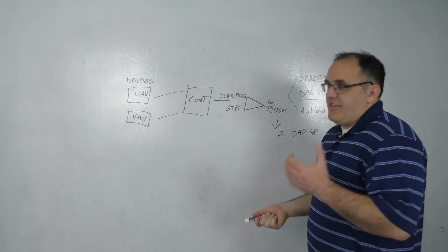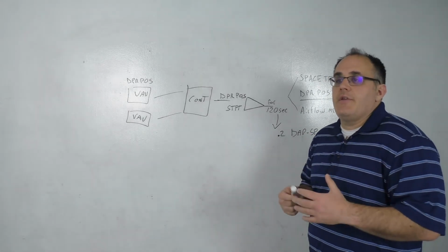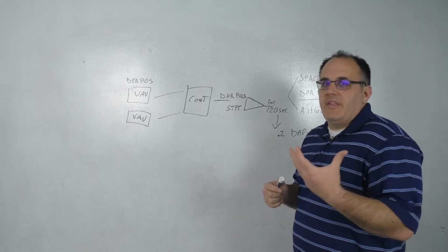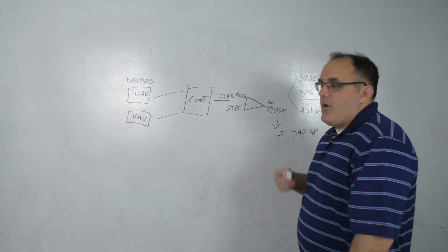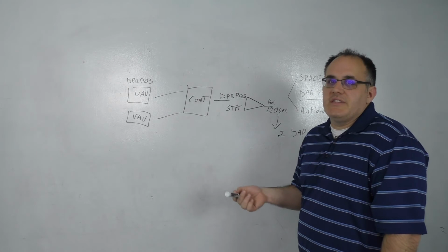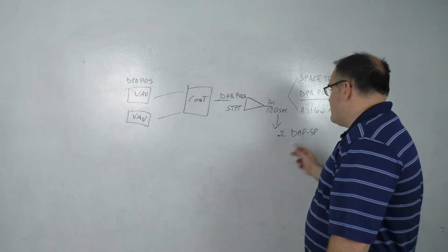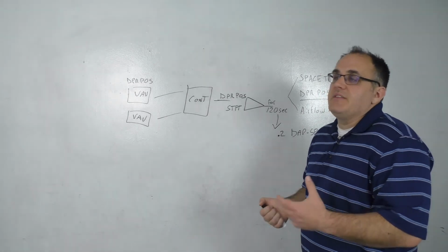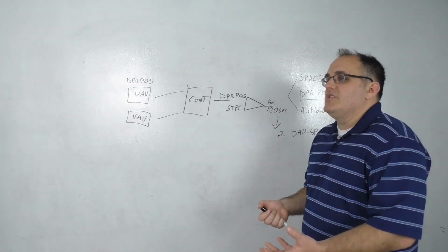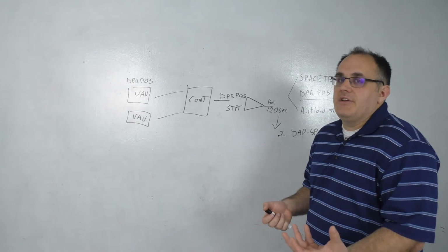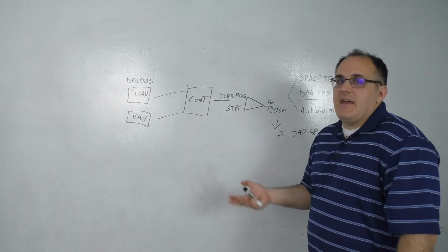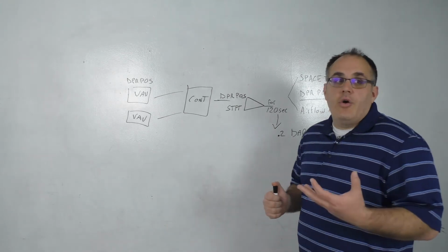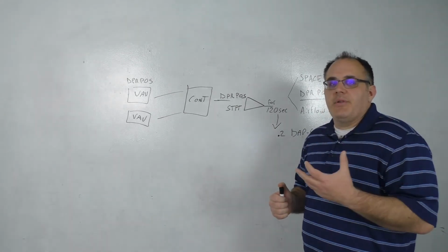So the theory behind temperature reset was that by increasing the temperature, the coil would have to open less. The theory here is that where you can't necessarily do temperature reset, what you can do is reset pressure, because less flow going through the coil means less BTUs being transferred to air, which thus is less demand both on the actual fan as well as on the coils. So that is how you're going to go and implement trim and response.